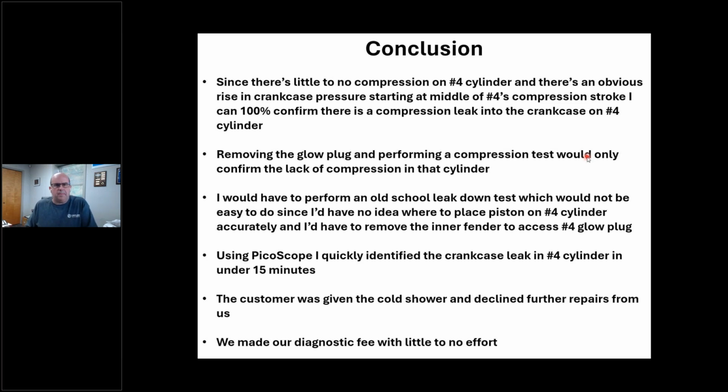Now, could I have rigged up air and put air in the cylinder? But don't I have to find where TDC is? Okay, how am I going to do that on an engine that's got no timing marks? You're working on a 6.4 with that big fan stator in there. Do you think you can get anywhere near that crank pulley? And you know those Internationals, they've got 4 bolts. They don't have a bolt in the center.